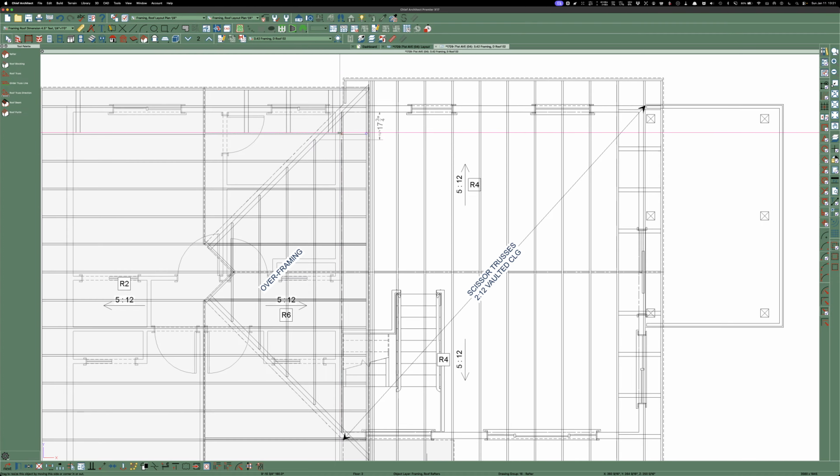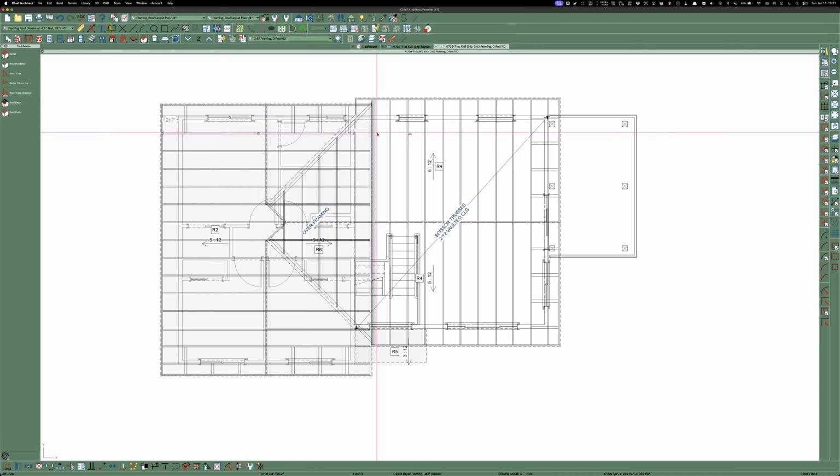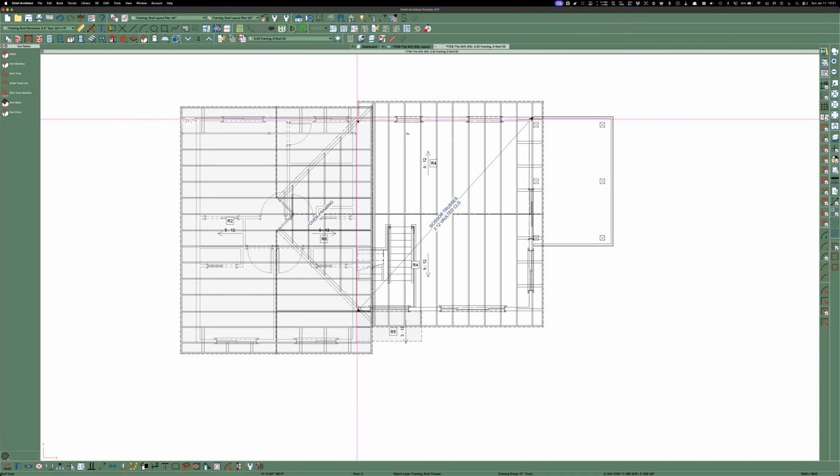So, what is it? Why? What are there, 2 sets of trusses here? Very strange. Anyways, I'm going to have to go through and manually pull the tails off of these, because you wouldn't have tails sticking down into the ceiling. And all of these trusses are scissor. These trusses will be standard tail out here, web truss flat across, and then they'll end right at the end of the wall.